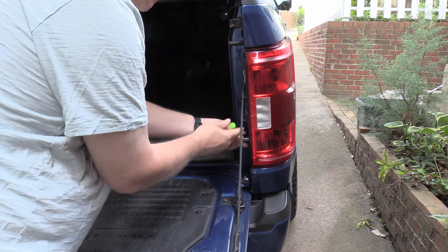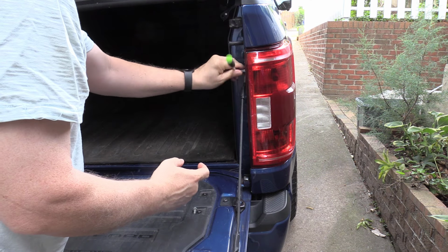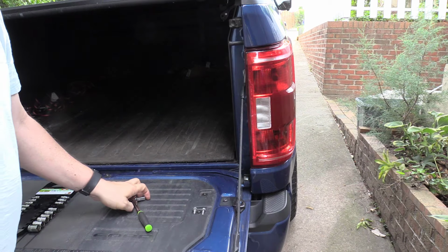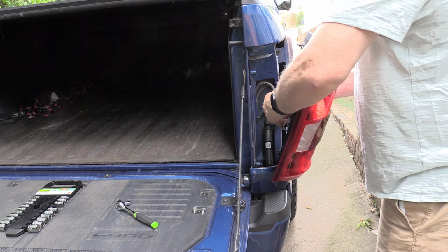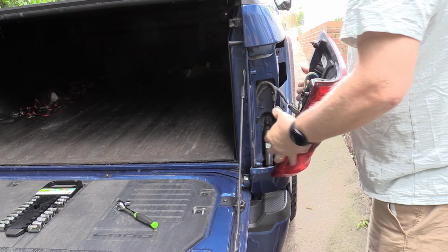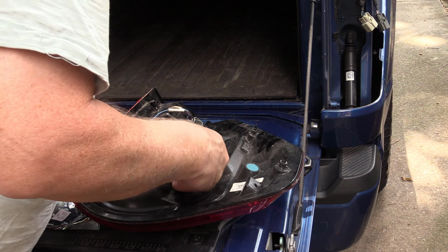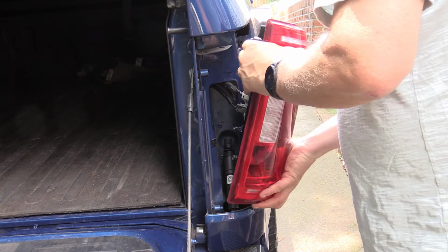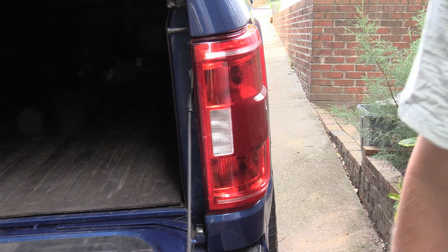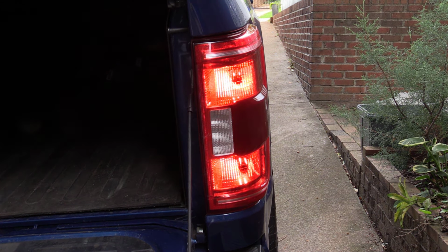Replacing these bulbs is a very simple job, just an 8mm socket with 2 screws that you need to remove, and then pulling out the main unit, making sure that you don't break any of the bosses that fit into the holes. There's 2 connectors to unplug from here so that you have the tail light module all by itself. And then it's just a matter of removing and replacing the actual lights. And then installation is the reverse of removal. And what I always do is, as I get this connected in, I give it a test fire before I screw down the 8mm screws again.